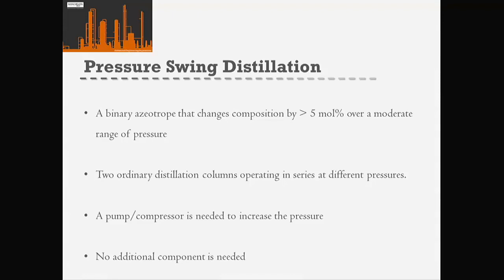So this brings us on to thinking, if we can now represent our distillation systems, and we can look at what feasible products and feasible separations we can actually do based on our vapor-liquid equilibria and our feed point, what we now need is to consider what potential options we have to actually separate azeotropes.